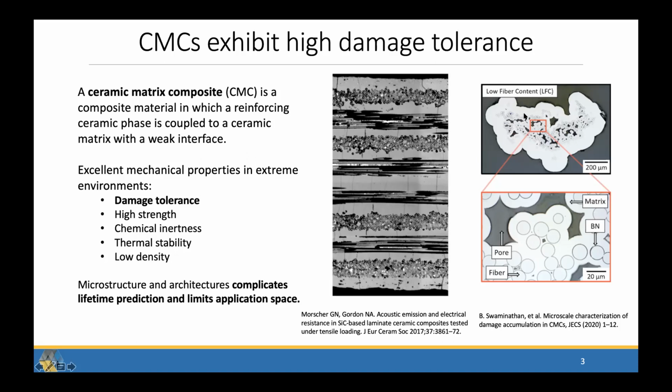This is what's called a mini composite. Its fibers are just aligned vertically with a matrix, and so we can pull them and have a limited set of deformation mechanisms that we can then validate. So we're starting with this question of, can we even identify damage mechanisms? And so we're starting with this unidirectional mini composite to try to answer that.